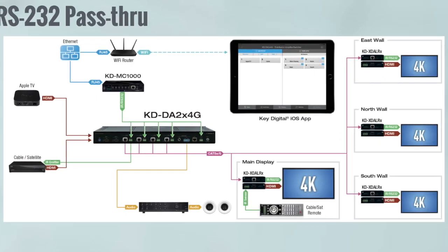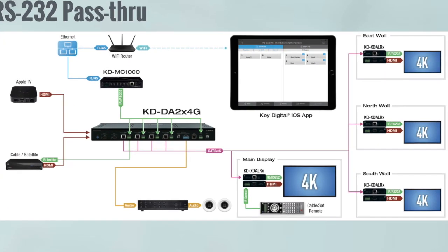You will feed in IR or RS-232 into each of the 3-pin Phoenix connectors that is located beside the respective HD-Base-T output, and that IR or RS-232 signal is output at the receive unit at each monitor or display.